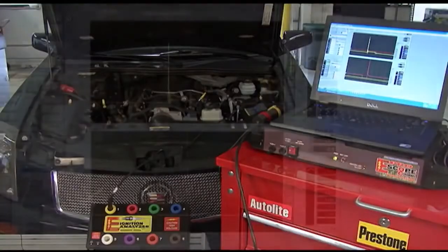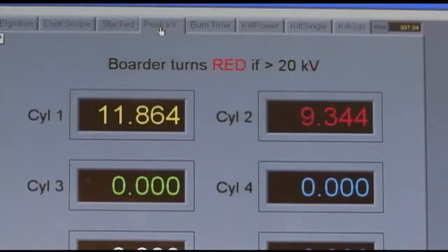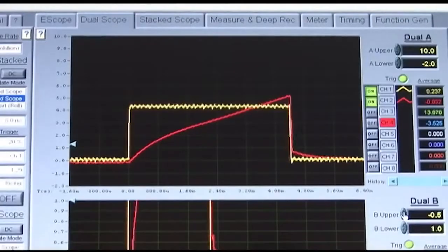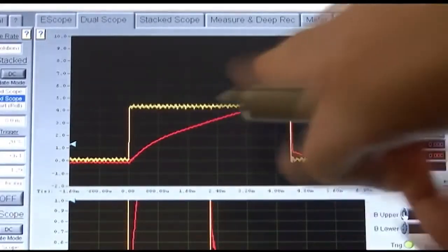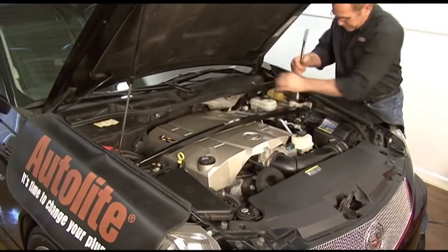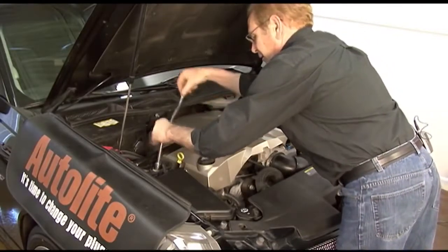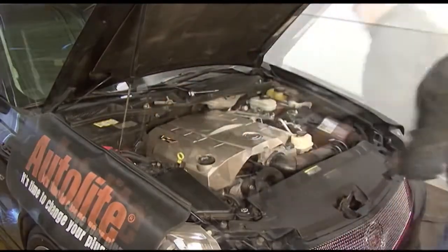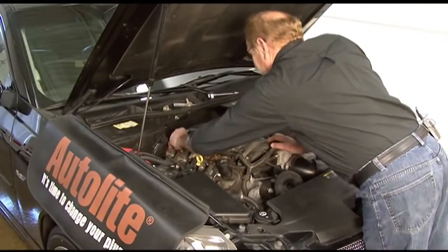Ignition-related misfires are very common. Start by measuring secondary voltage and spark duration if possible. In a coil unplugged system, use a low amp current probe to measure the coil's current draw and inspect the on-slope and oscillations at turn-on. Using a low amp current probe can be really helpful when you're dealing with one of today's newer engines, where access to the spark plugs can require a lot of removal and replacement of engine components and covers.